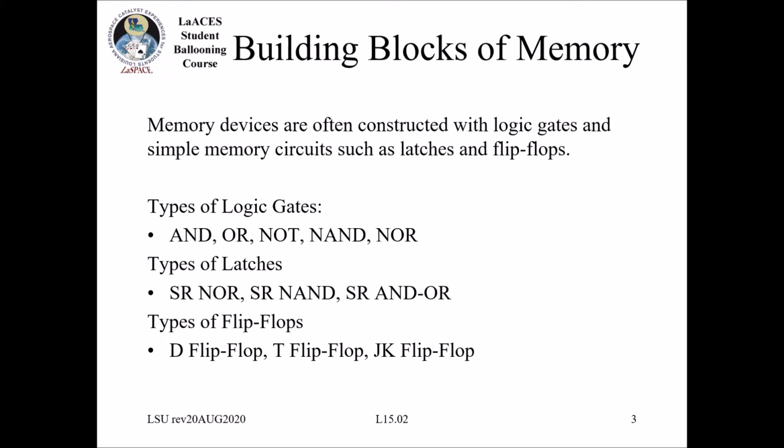A latch is something that would stay in the state, so you would turn it on and it would stay on. And a flip-flop is something that you can send a signal to change it from a true to a false, right? This is basically how you build up a whole bunch of these things together, and combining these is what gives you your memory storage.